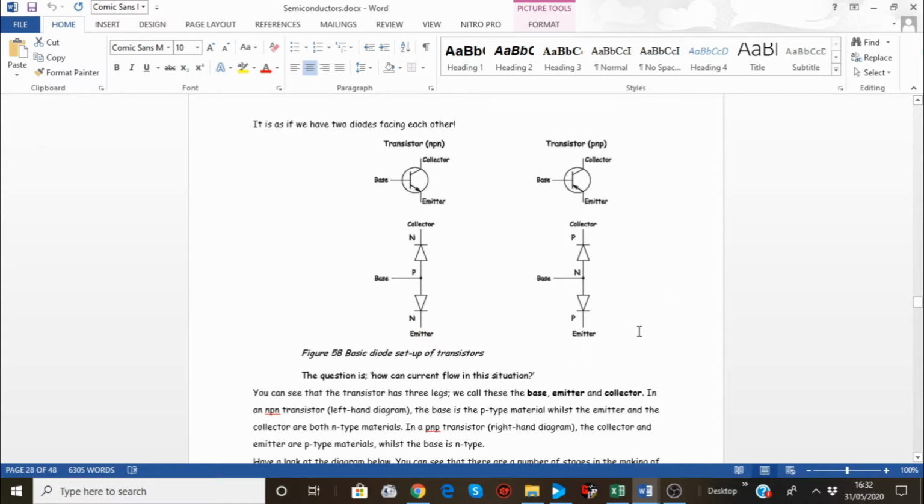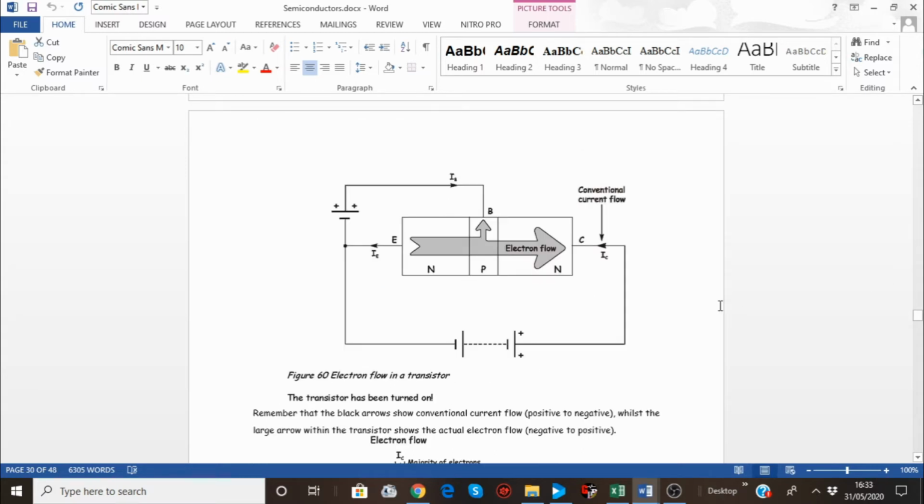You could basically consider these transistors as 2 diodes connected face to face or back to back. So if they're connected like this, in case of NPN, then that's how they're connected. So how it works is that if you consider those NPN material inside the transistor, and these are 3 pins coming out, base, emitter, and collector. You connect this collector emitter to a big voltage, bigger battery, and between base and emitter you have a smaller voltage.